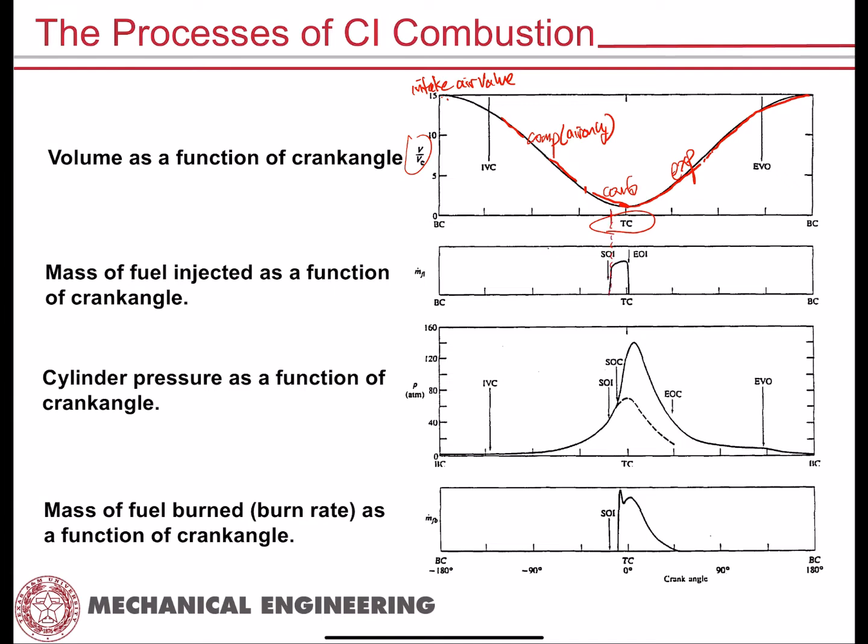And then somewhere near top dead center, and in this case it happens to be right here, so that's what the second plot is showing us, the fuel delivery rate. I'll talk about this in just a minute. But somewhere near top dead center is when you start to inject fuel. This is what we're going to call SOI, which stands for start of fuel injection.